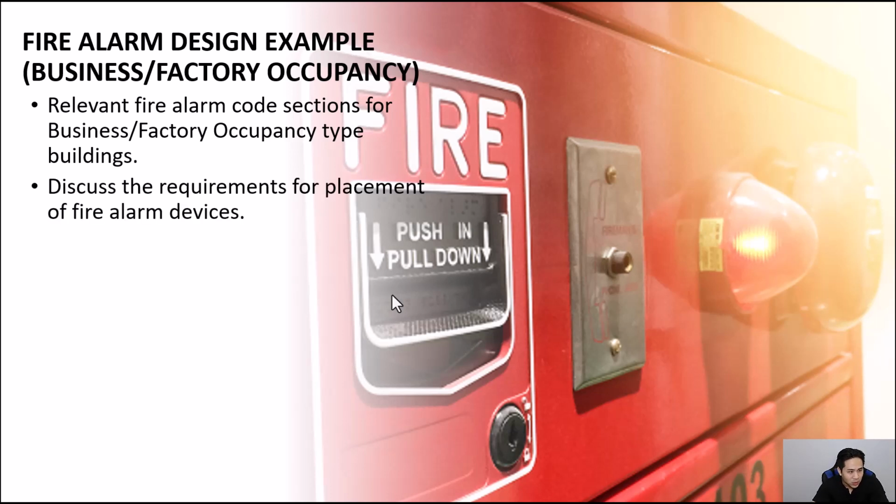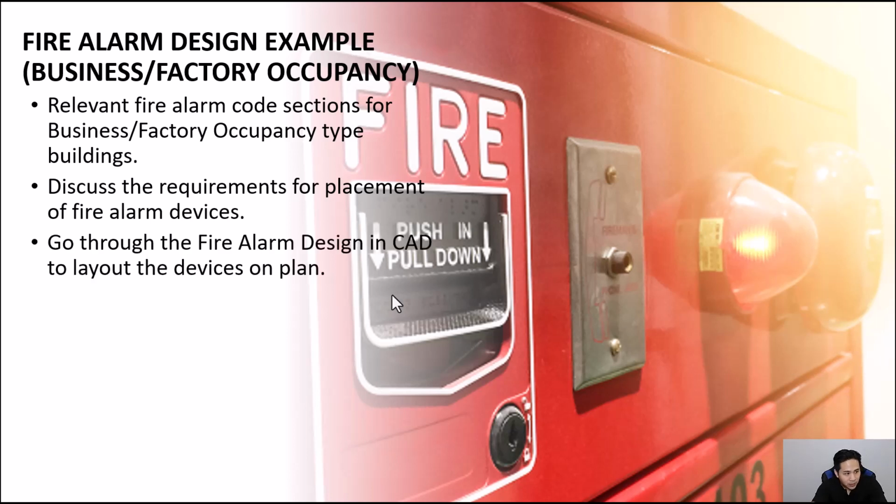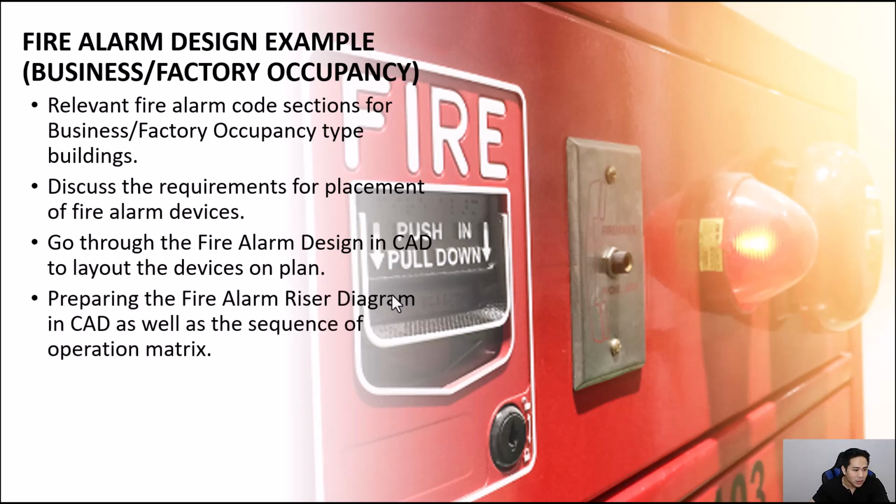Then we'll discuss the requirements for placement of the fire alarm devices throughout the plans. Then we'll go through the fire alarm design in CAD to lay out the devices on the plans. And then we'll go into preparing the fire alarm riser diagram, as well as the sequence of operation matrix, which I'll explain what it is later in this video.